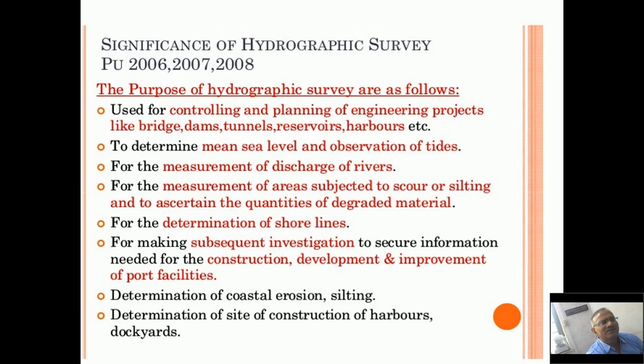So what is mean sea level? While establishing any benchmark, the reference point is the mean sea level. Before the independence, the reference point was in Karachi. So we were taking the mean sea level at Karachi, but now for our convenience in India also, at so many locations, you will find the mean sea level. That is the one particular location at the point in the sea where your reference level is 0.00 meter, and with respect to that, other levels are measured or fixed.